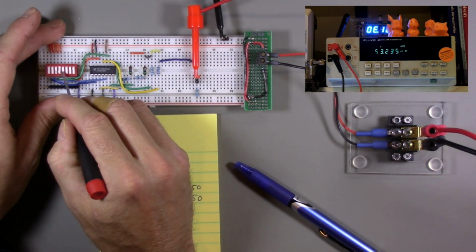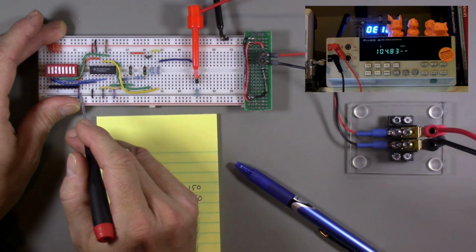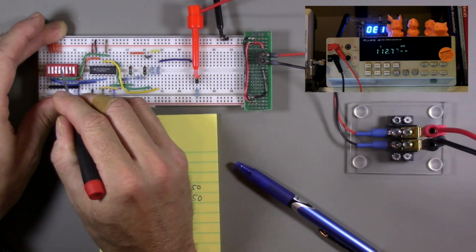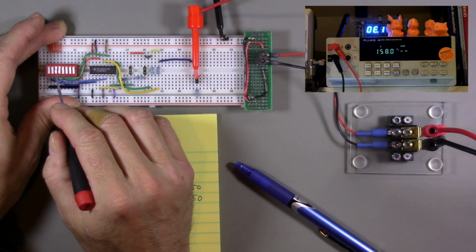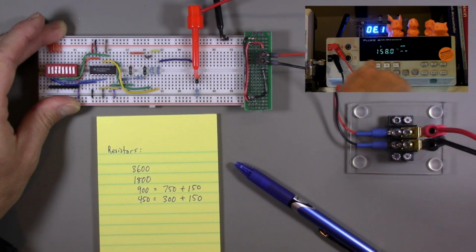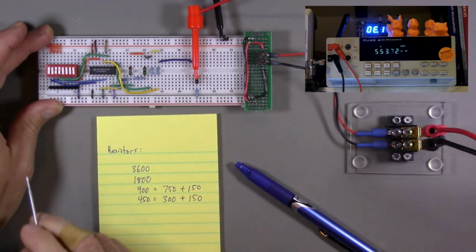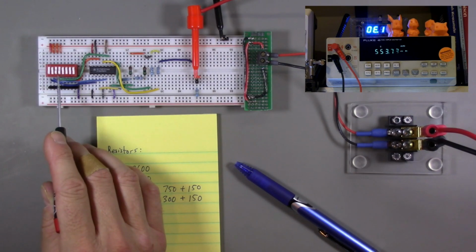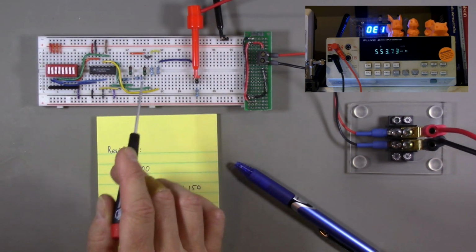All right, so let's turn that off and then turn the 2 on, the second least significant, and that gives us 104.8 millivolts. And then I will turn the least significant one on again. This basically corresponds to the binary value 3, and that produces 158.02 millivolts. So that's the basic idea. As I select various combinations of these dip switches, I'm essentially encoding a binary value that is then converted into an analog voltage by our resistor network here.